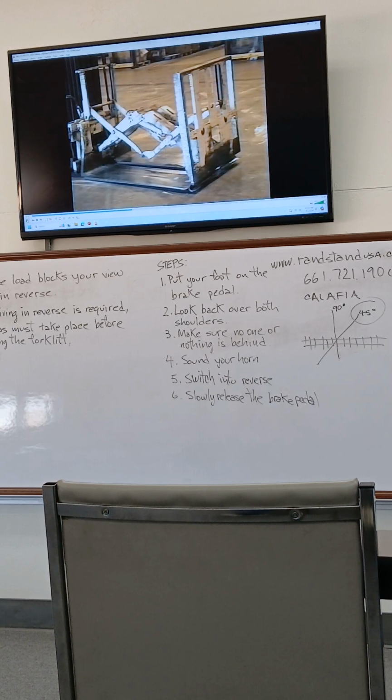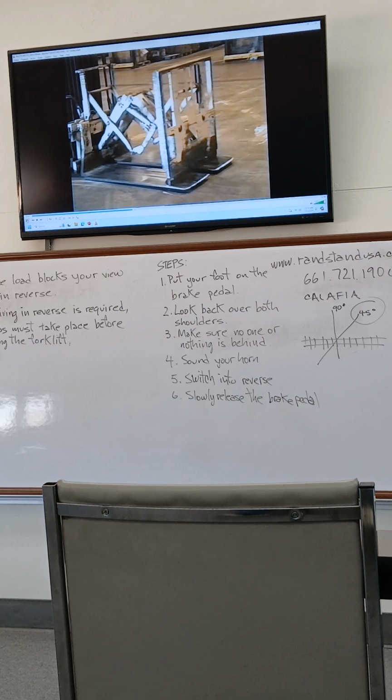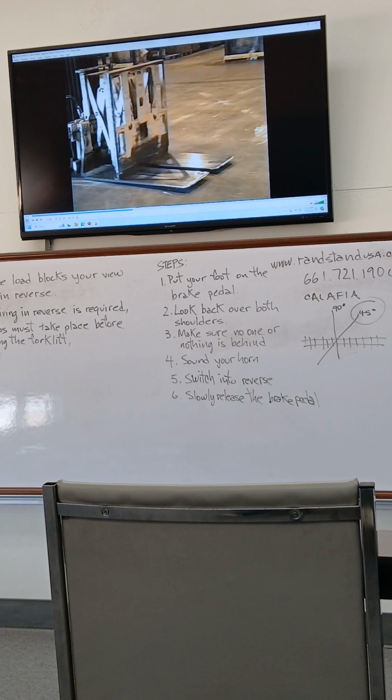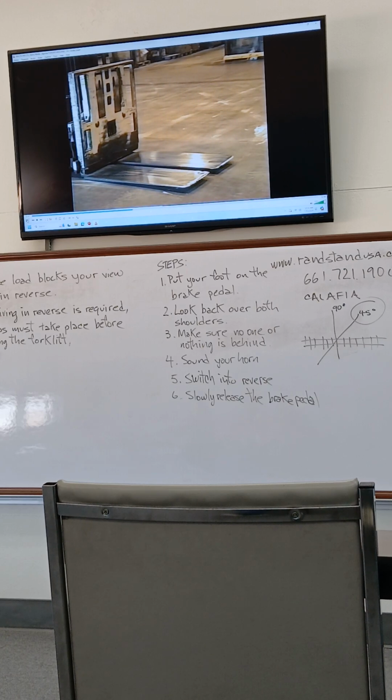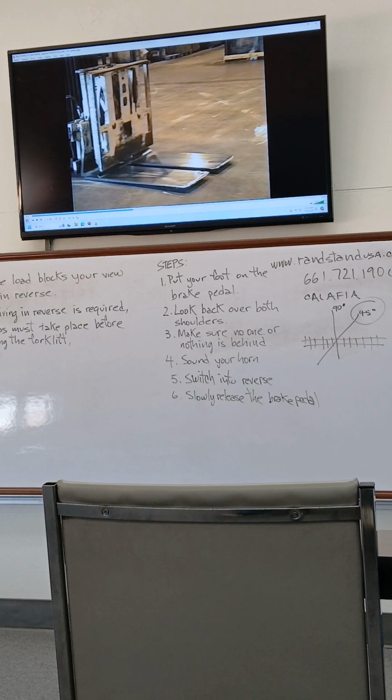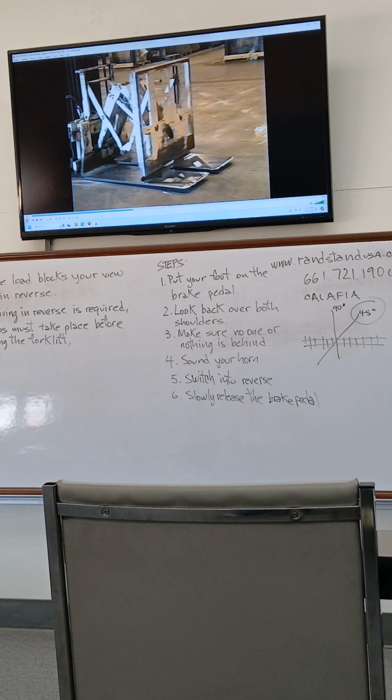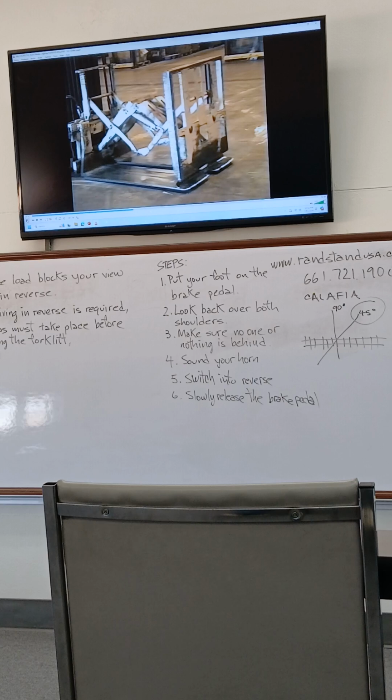Forklift operators must fully understand how each particular attachment changes the safe lifting capacity of the forklift, the stability of the truck, and other potentially hazardous changes to the forklift on which you are using the attachment.